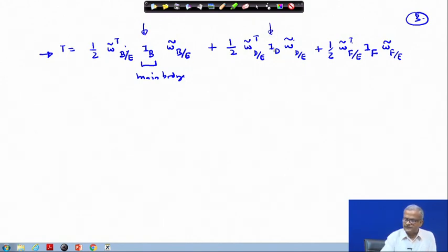If you are choosing along the principal axis, you will get all these quantities as a diagonal matrix I d, I f. And the things will get simplified, and if you are aware of the corresponding angular velocity with respect to the inertial frame, the work becomes easy.